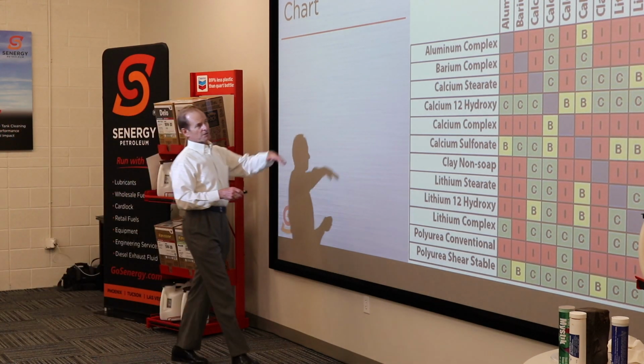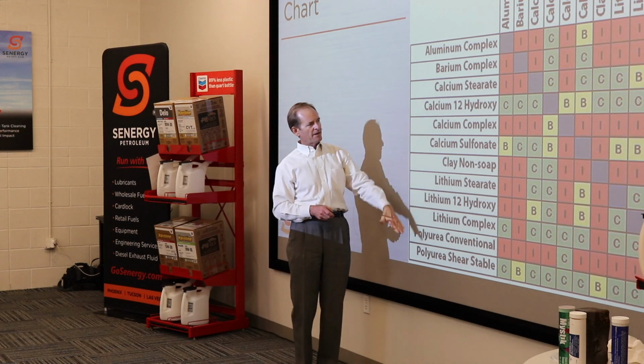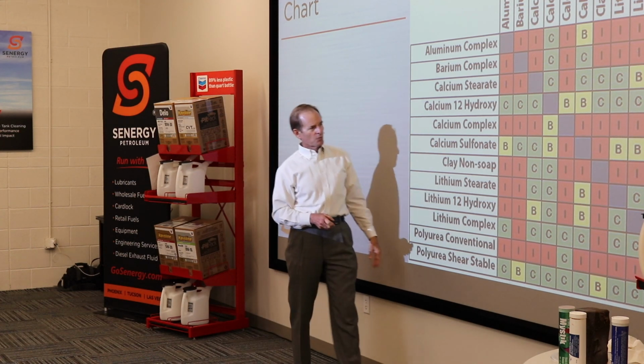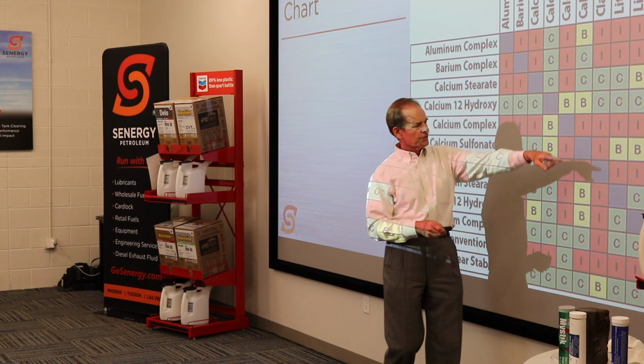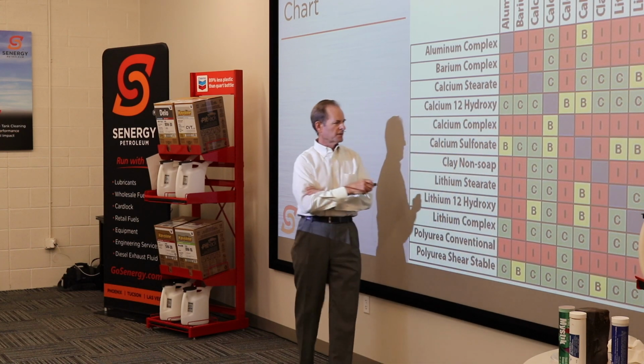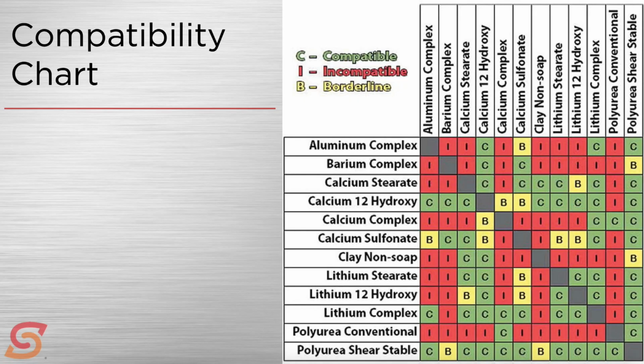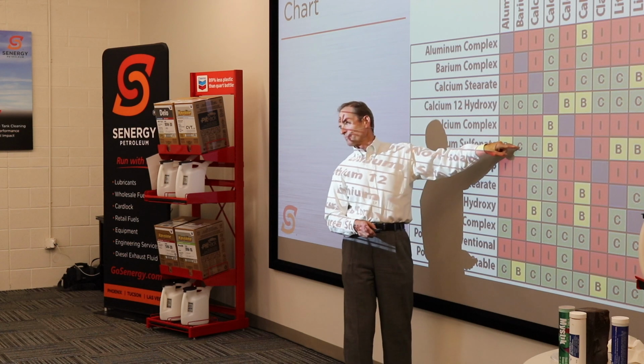And the way these work, you look at the soap that you have, and the one you're wondering about, and you look at the intersection and find out that a clay-based grease and a lithium stearate grease, they got the big I, they're incompatible. Okay? Whereas calcium sulfonate grease and a barium complex grease would be compatible.